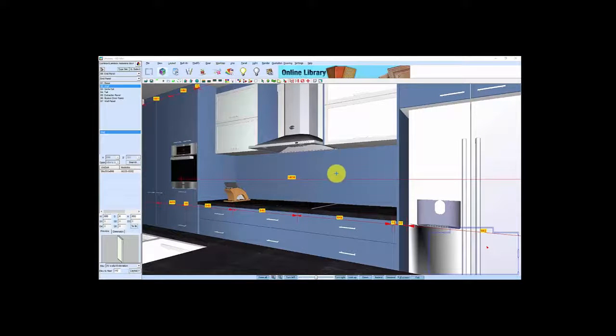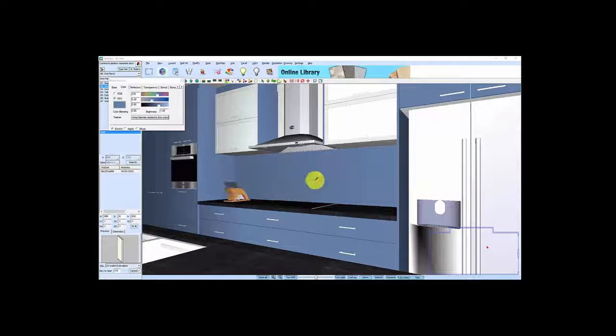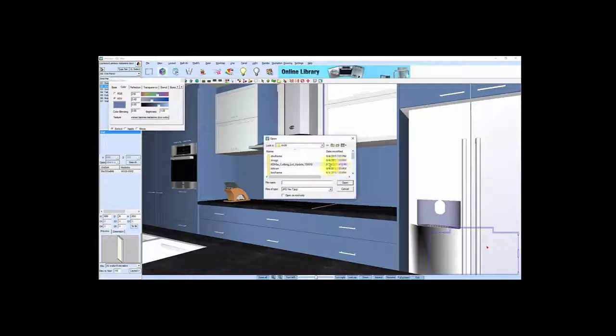So from there, what I'm going to do now is change the color of the splashback so it's something nice and bright so you can see it. So what I'll do is click on this button up here, which is Material Editor. So I'll click on that. Okay, go to color, select melamine, go browse, basically go to where I've saved some JPEGs on my system, on the desktop.